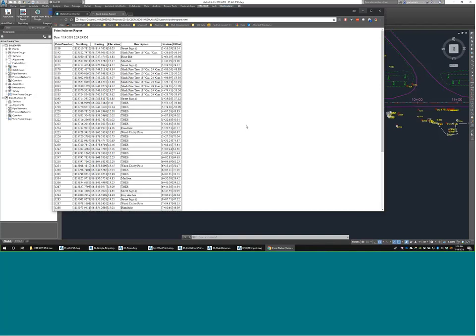We do get a lot of questions from time to time about units and where in the interface you select units. One of our goals when we created these tools was to make the interface for them as absolutely simple as we could. So we made the decision a while back when this utility was created that we're going to look at whatever the defaults are set up in the ambient settings for Civil 3D and use those values.